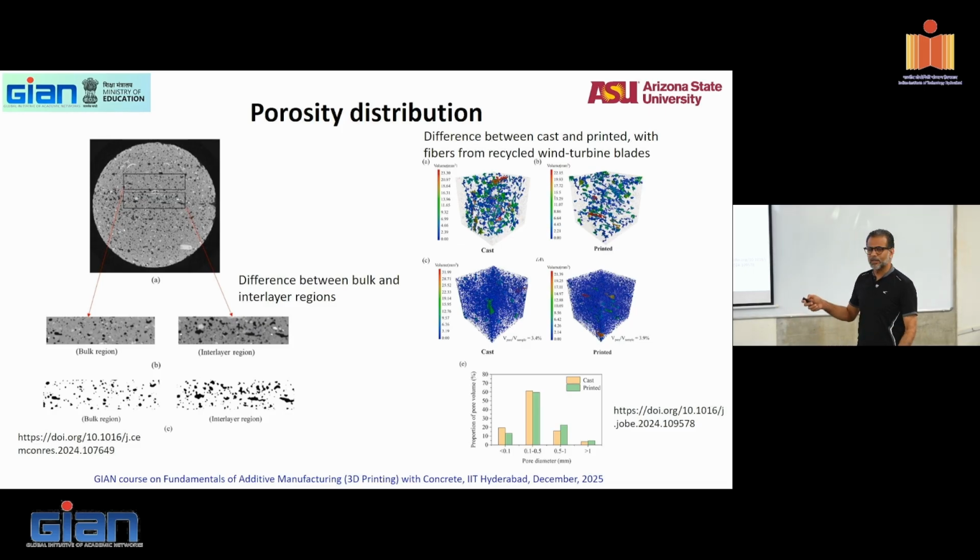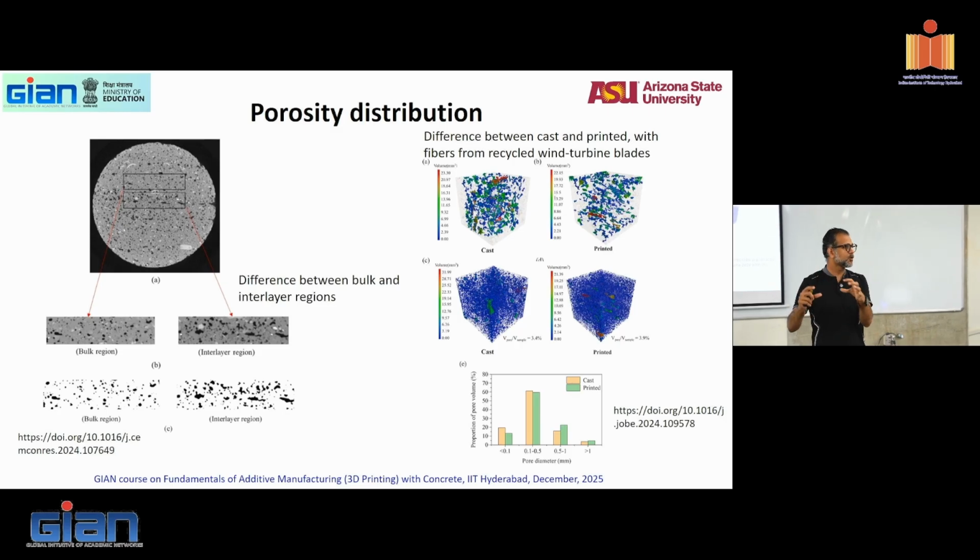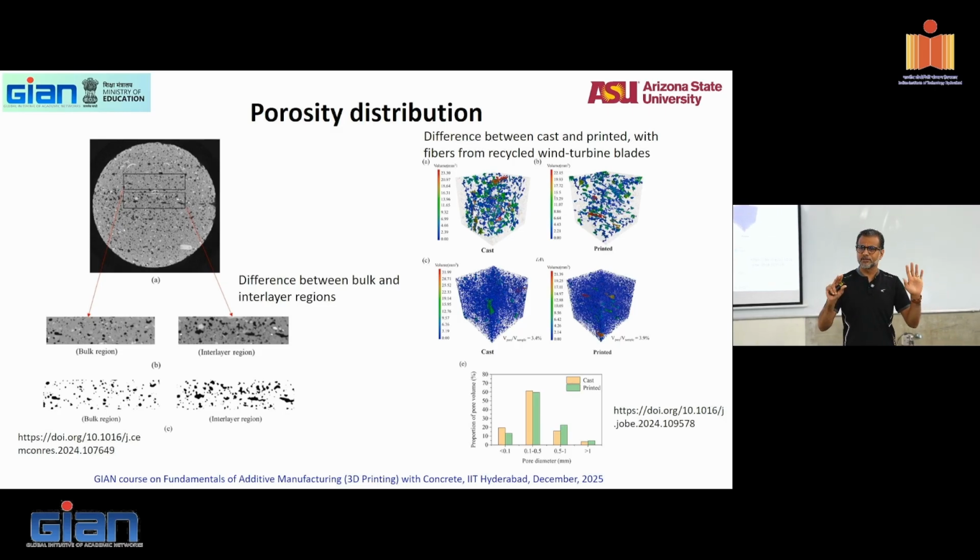You can threshold it in different ways and find all of these shapes. I told you about spheroidal voids; ImageJ can easily identify and quantify void shapes, and you can find them in terms of directions. You can do lots of interesting work. Then, if you want to go to the next step, you can test those specimens in compression, tension, or shear, whichever way you want, and look at the influence of porosity and void sizes on these properties, which is very useful research.